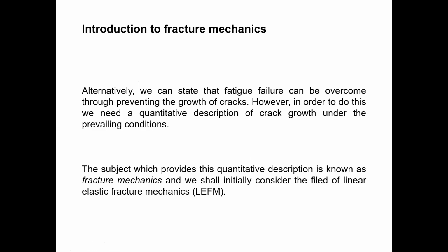But you don't have any idea, you just calculate the Kf as a stress concentration around the stress raiser, and you get one particular constant value for the Kf. So you don't have any idea quantitatively about that stress consideration. You just have this one single value, you don't know how it varies. So those variations, how to grow that crack and how to initiate that crack, all those things quantitatively we will describe during this lecture.